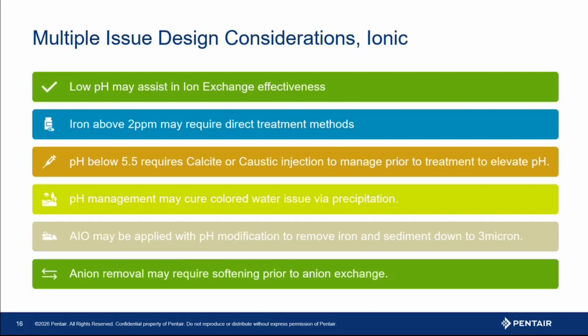Make sure you understand whether or not you have actual dissolved iron versus organically bound iron in the water. And remember, when we oxidize iron, we are creating a dirt load. So make sure you evaluate that dirt load that you've created in that removal system, like an AIO, that we're getting that tank backwashed thoroughly enough at the first time you see it after a startup. Make sure that backwash is getting that tank clean. We don't leave that stuff in there.